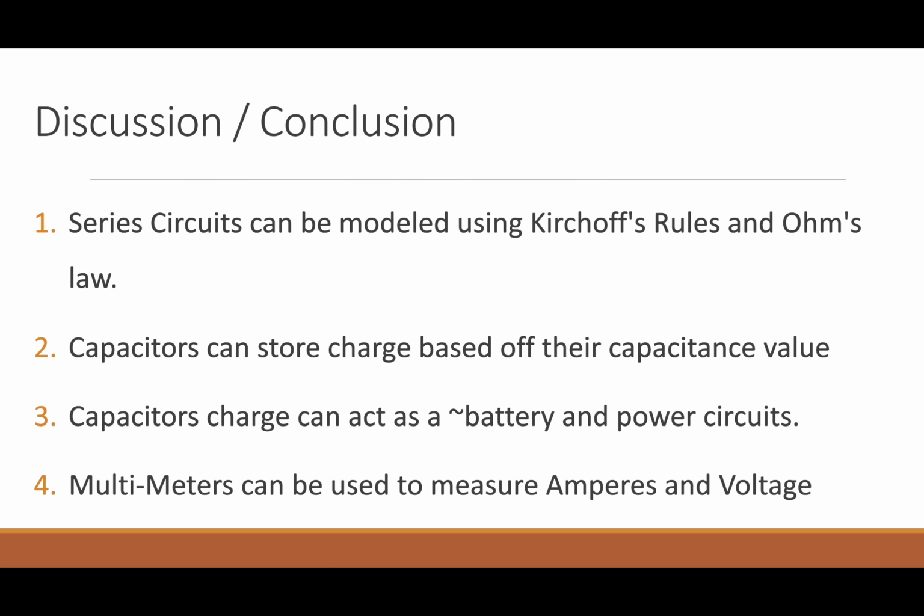Discussion/conclusion. Series circuits can be modeled using Kirchhoff's rules and Ohm's law. Capacitors can store charge based off their capacitance value. Capacitors' charge can act as a pseudo battery in circuits. And multimeters can be used to measure amps, as ammeters, and voltage.